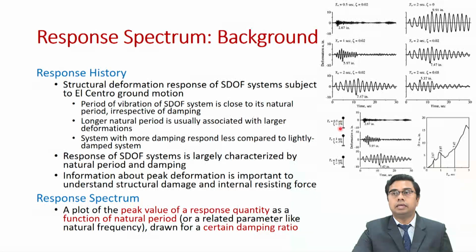Each of them has 2% damping, but the natural period is varying at 0.5 seconds, 1 second and 2 seconds. These plots are for structural deformations for these single degree of freedom systems subjected to El Centro ground motion, and are very similar to these plots as we have seen. We will decode what is the peak value from these plots, and we will plot them as a function of